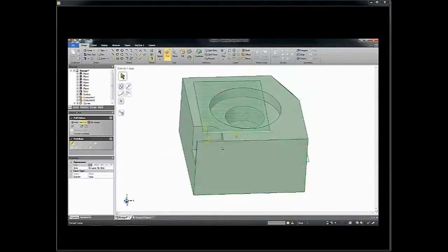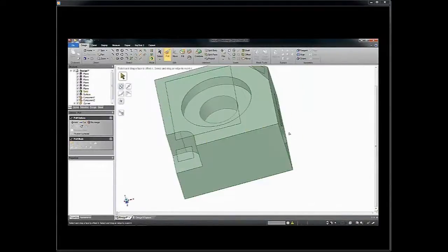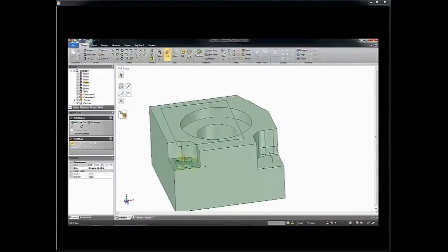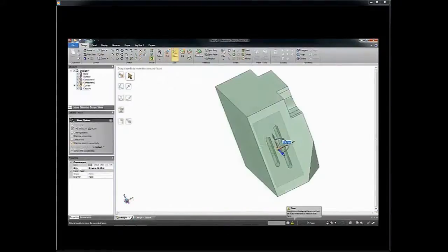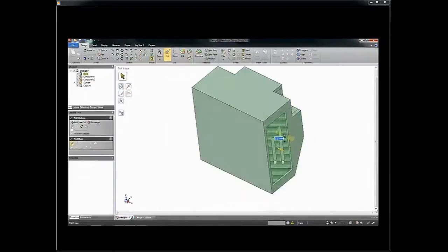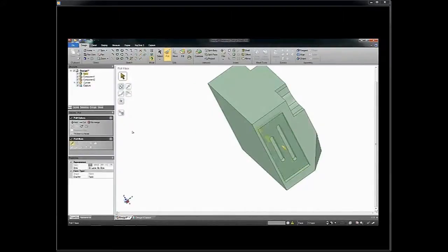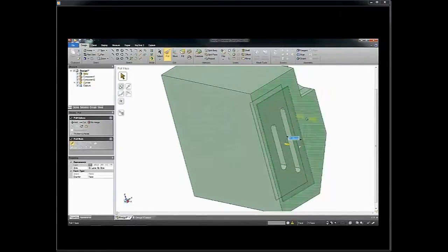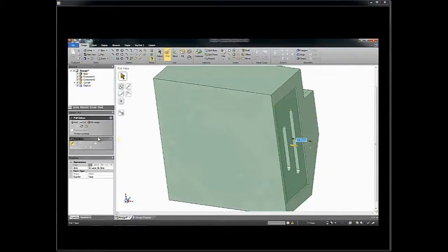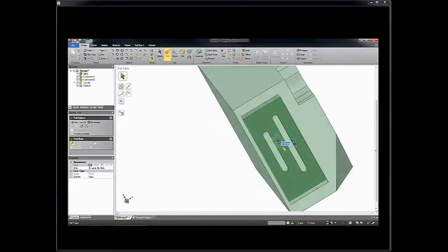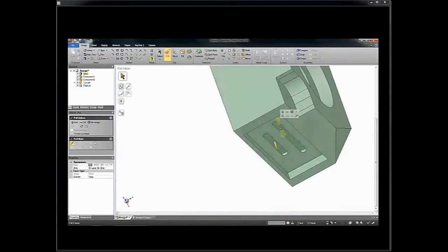And so we leverage those tools quite a bit. Here's a good example of these little cutouts where, after they're created, because they weren't created tall enough, they don't completely intersect, but it's really easy to take that face and do what's called a pull, where you just pull it right through that face. Again, that's one of the nice advantages of direct modeling, that it's really quick and easy to just click and interact with faces on the model without having to do a lot of digging through the feature tree to find that particular sketch or feature in the tree.